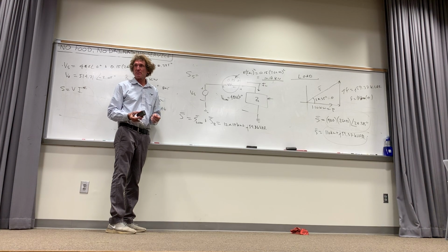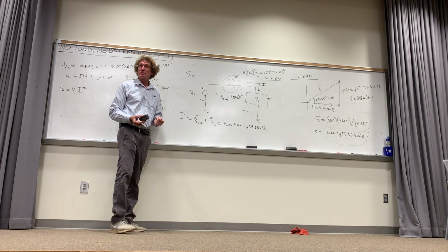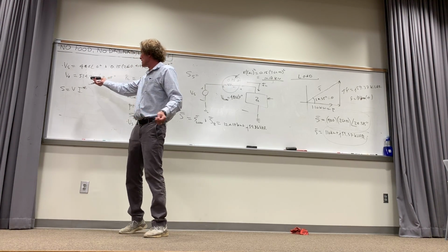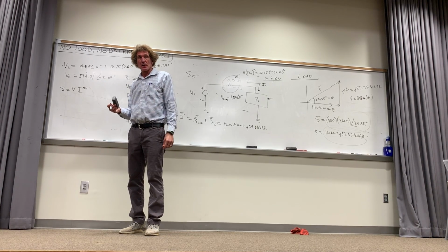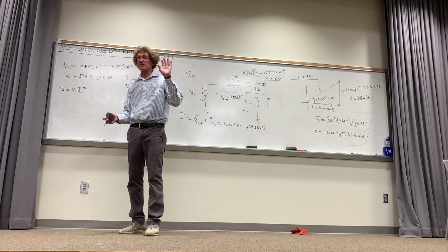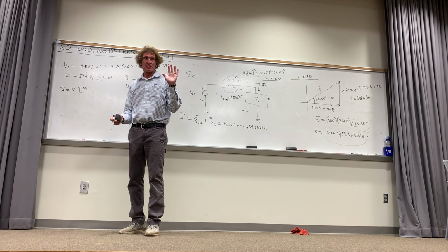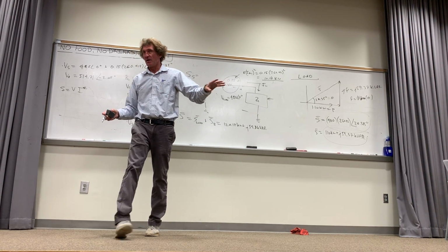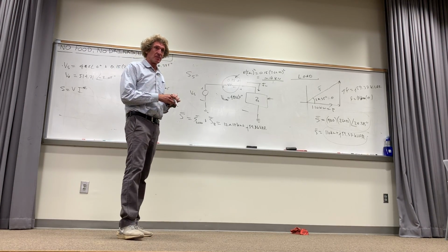That's the total one. It doesn't matter what the subscript is. The voltage on the far left, that is the RMS of the source, right? That's the source voltage right here. And that's RMS? Yep, all the voltages are RMS, unless there's some unforeseen reason not to use that. And this is all steady state. It means it's a constant frequency sinusoidal variation. There are no transients here.